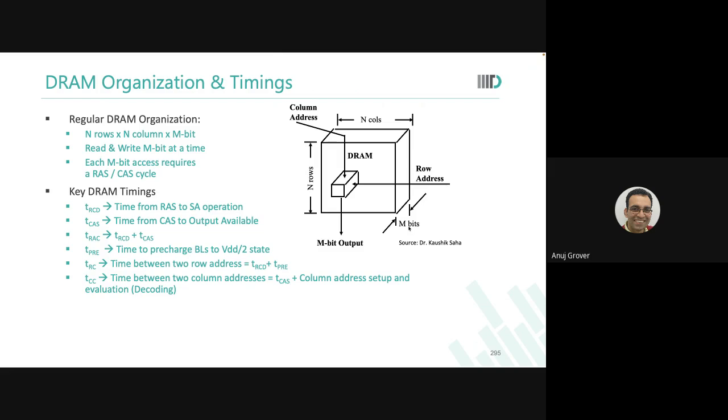And what we'll see later is that a small buffer is put below this cube. Small buffer does not mean that tiny. It's like an SRAM that is put there, which stores all the information that comes from the DRAM in the intermediate state, so that whenever the output enable starts to come, my DRAM can start to get data out. Okay.